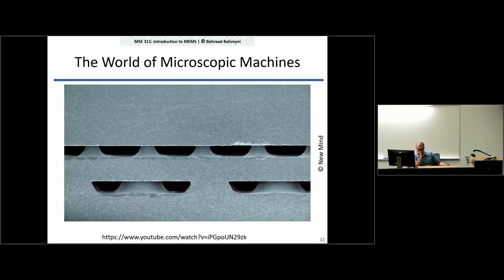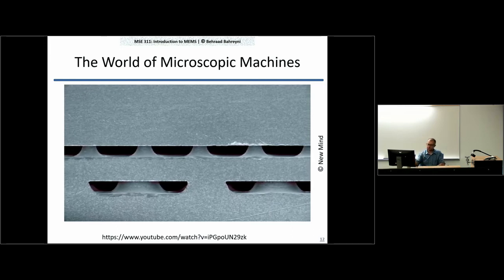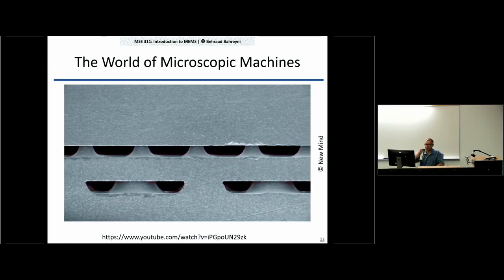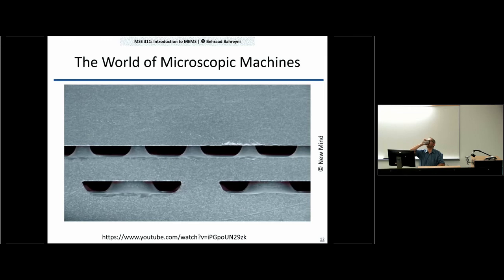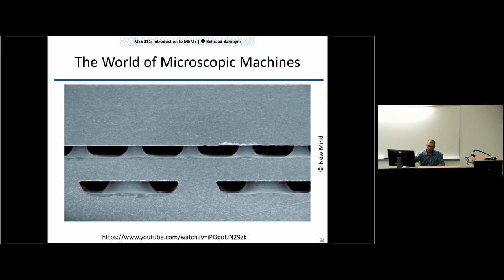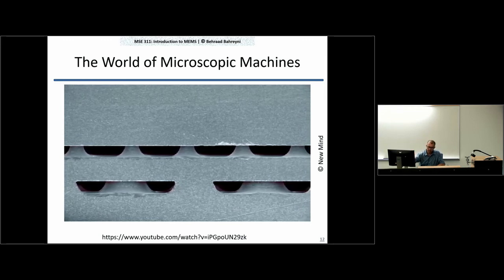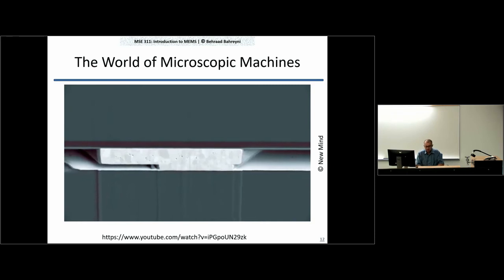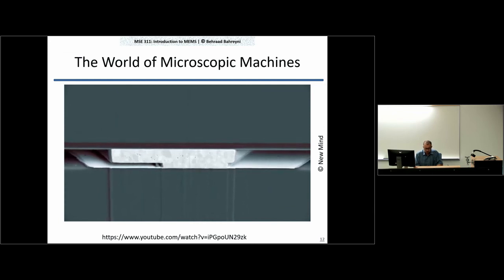In order to form more complex and larger MEMS structures, micromachined silicon wafers can be bonded to other materials in a process known as fusion bonding. It's a technique that allows the seamless integration of multiple layers via atomic bonding between them. Fusion bonding allows for the use of more exotic materials such as metals, glass, ceramics, and even organics such as polymers, enzymes, antibodies, and DNA.